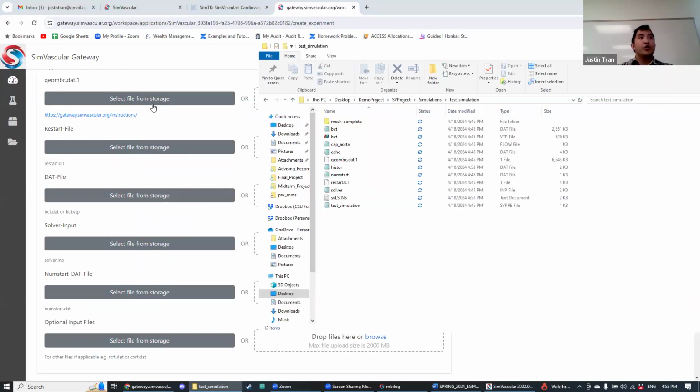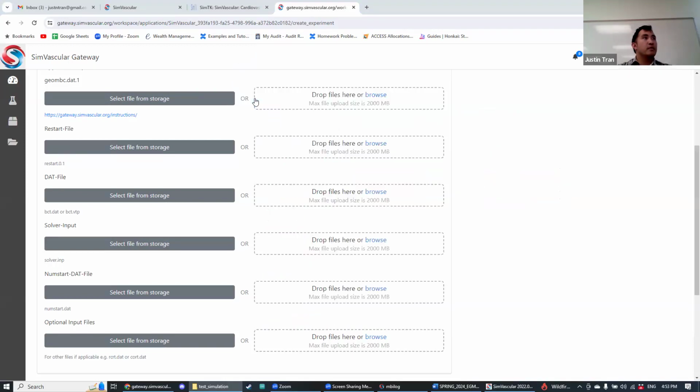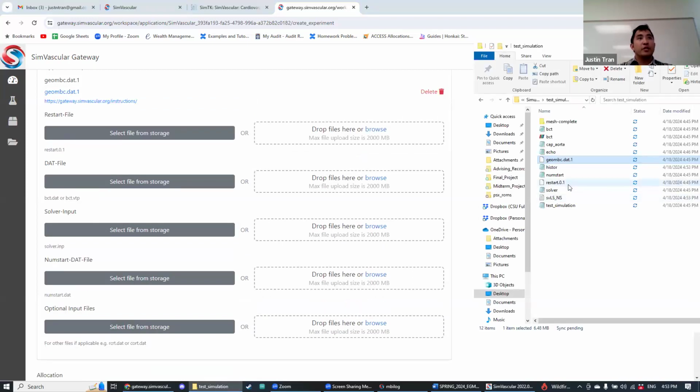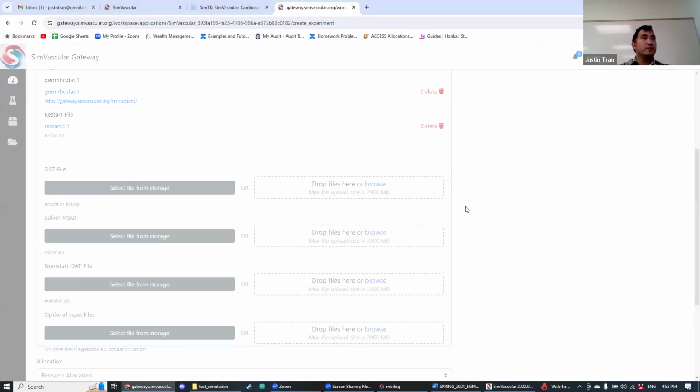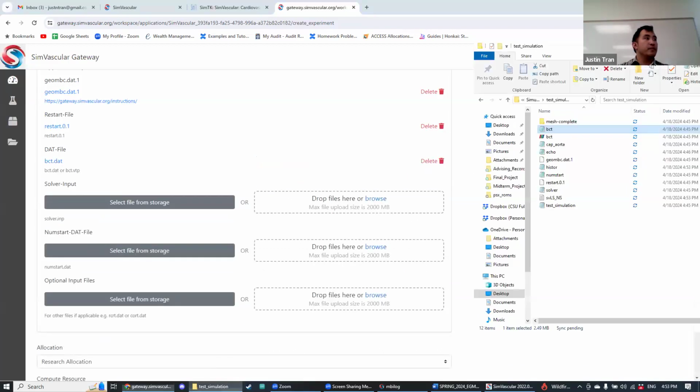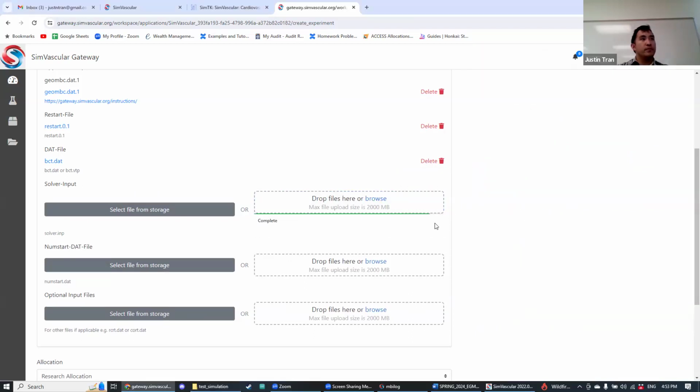So you need to upload geombc.dat. I'm going to go quick and drag this onto here. That uploaded geombc.dat. We need to upload the restart file. The restart file is restart.0.1. So I'm going to click and drag this here. Next thing is the DAT file, the one called bct.dat. So I'm going to click and drag bct onto here. The next file that we need to upload is the solver input. There's a text file here called solver that you're going to click and drag right here.